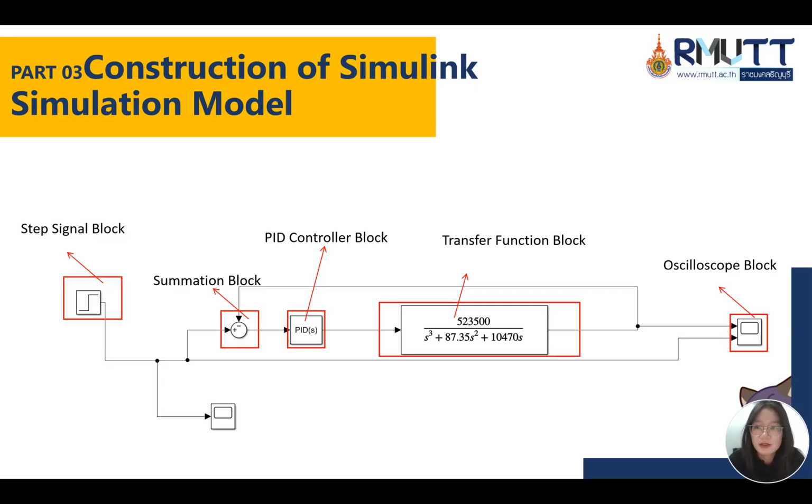This is part 3, construction of the Simulink simulation model. Next, I build the simulation model in Simulink. Please look at this diagram. The step block provides the input. The summation block calculates the difference between the feedback signal and the input signal.